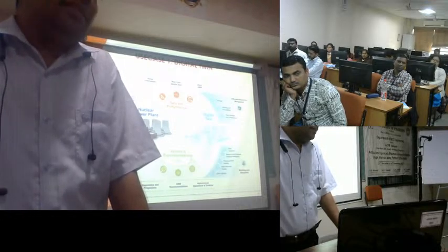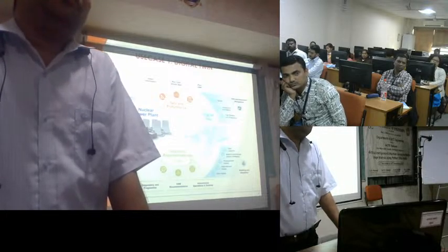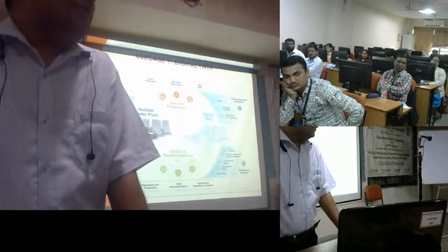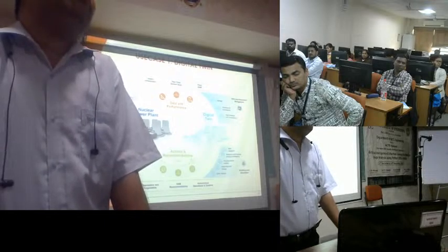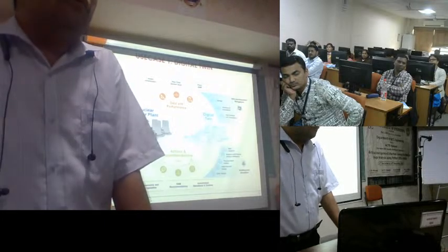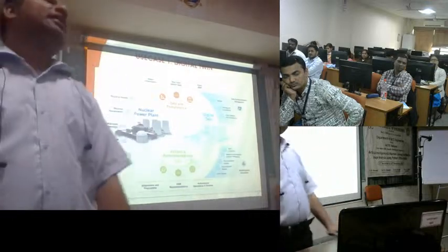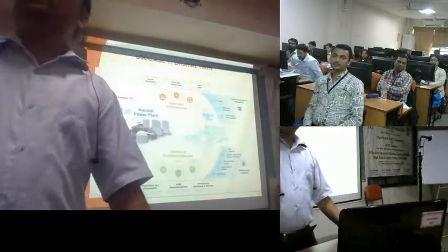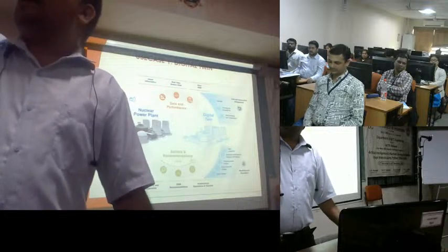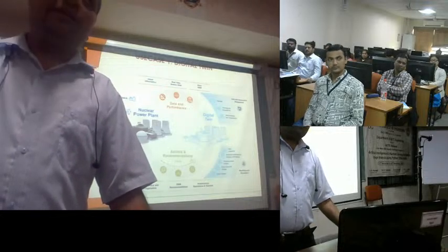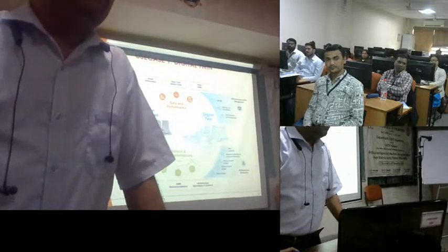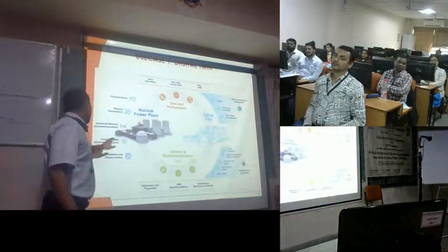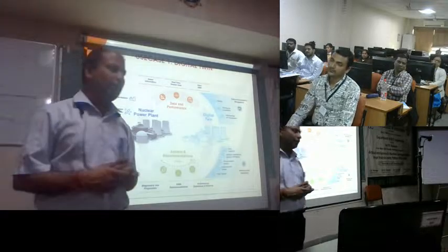You can increase the power, decrease the power. You can monitor the status of the different equipment, and you can give commands to the field instruments, for example, closing the valve, opening the valve, and so on, right? So all these things are done in the control room. You do have a lot of alarm windows, where if any process is deviating, the alarm window will blink, so that the operator's attention goes to the alarm windows. So these things you need to model. This is the computing and networking systems you need to model.